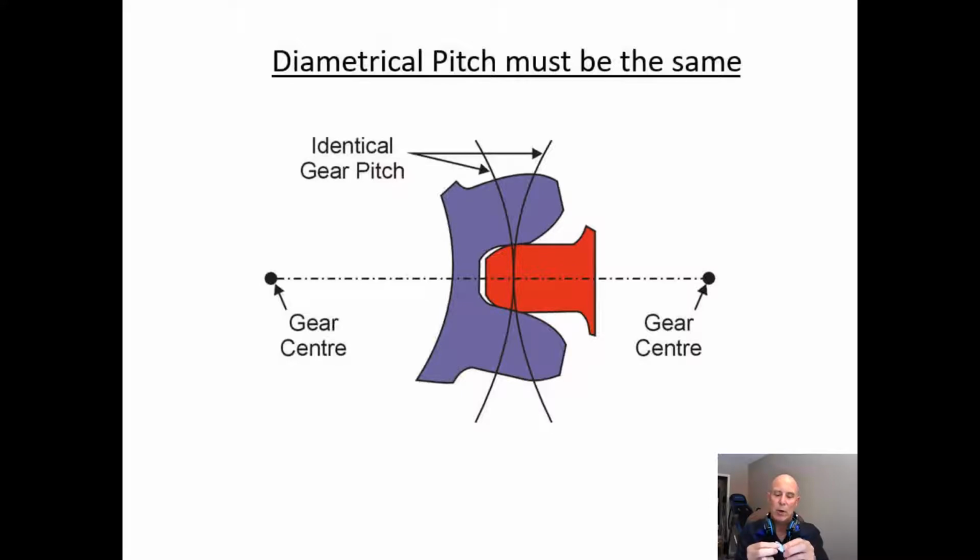So by putting it on here, we can rotate it around till it runs true. Now even though it's a metric gear set, it's 26. So on the metric scale, we would take this here and run it on here, and it's a module 1.